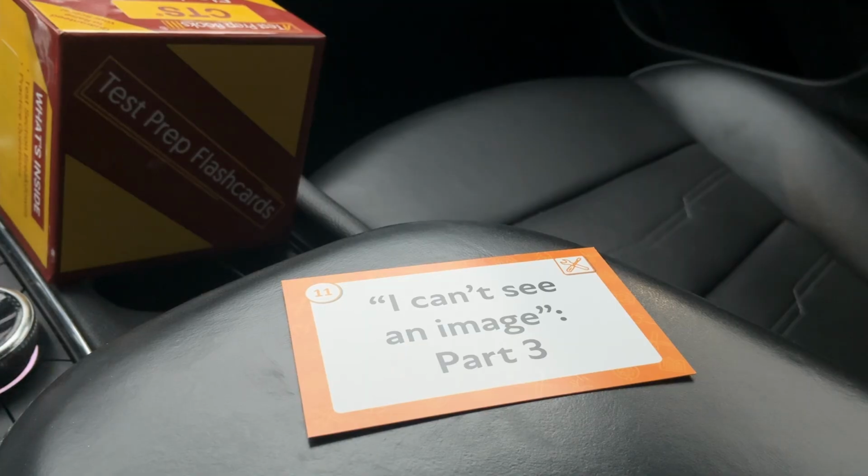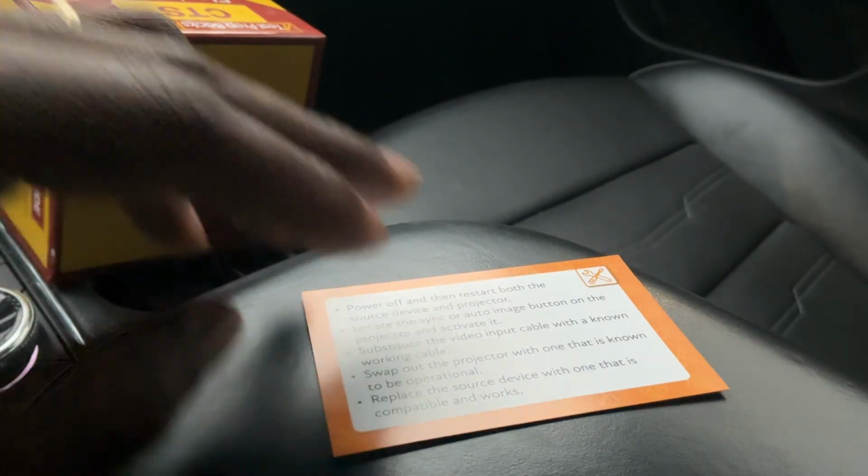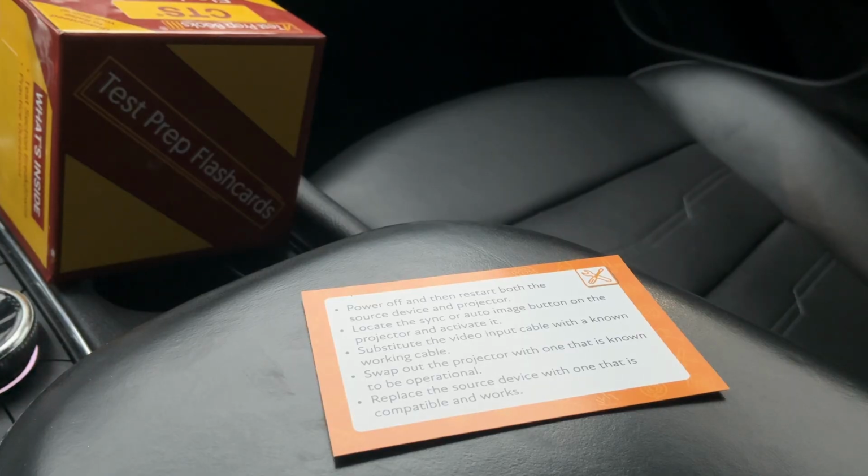I can't see an image, part 3. Power off and then restart both the source device and projector. Locate the sync or auto image button on the projector and activate it. Substitute the video input cable with a known working cable. Swap out the projector with one that is known to be operational. Replace the source device with one that is compatible and works.